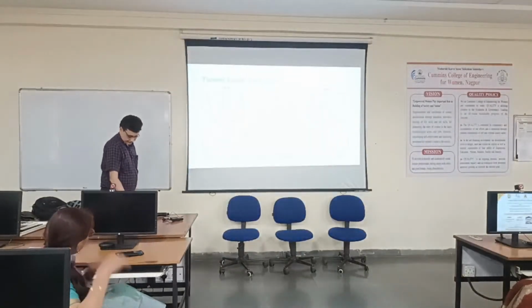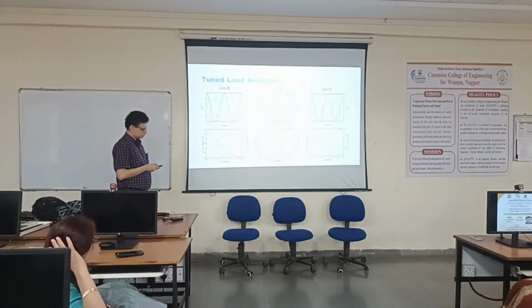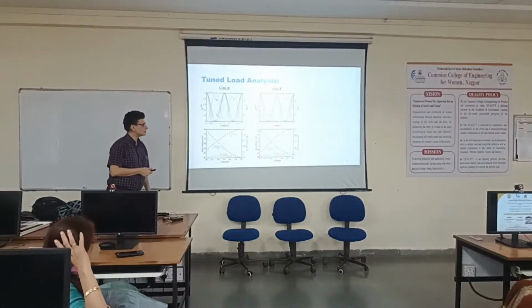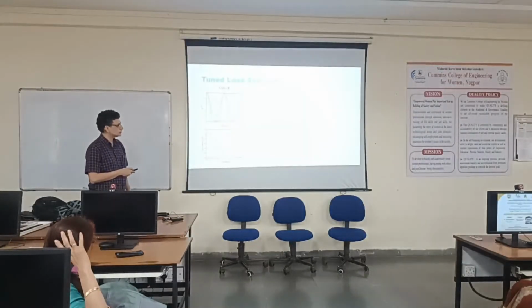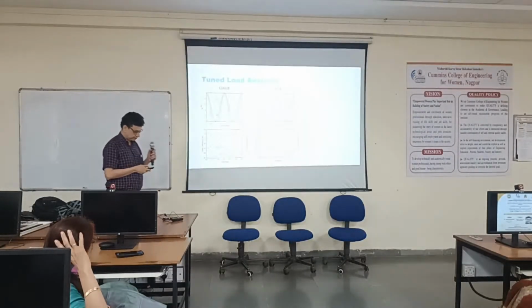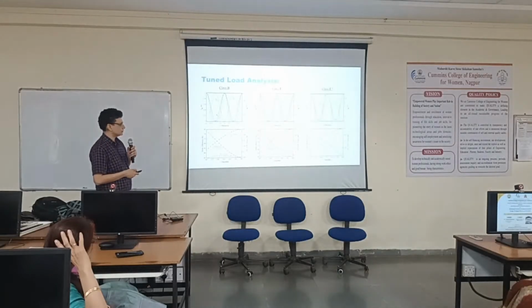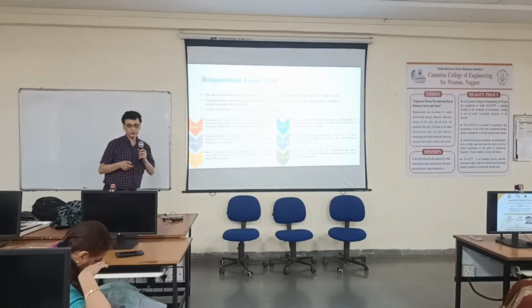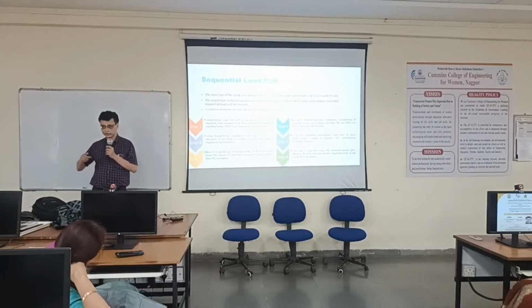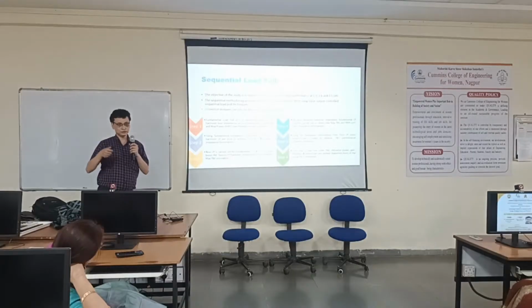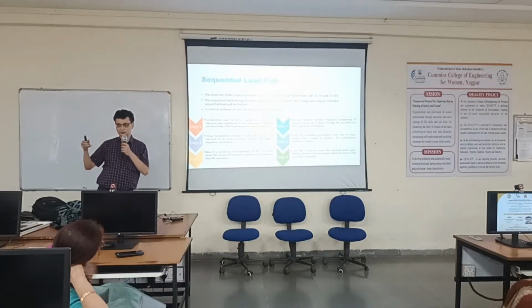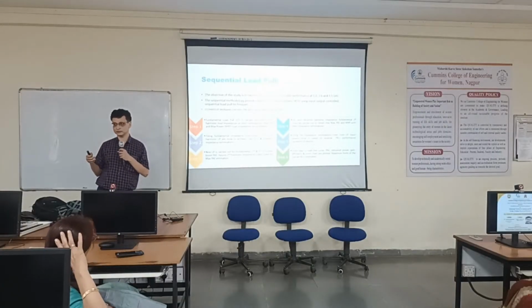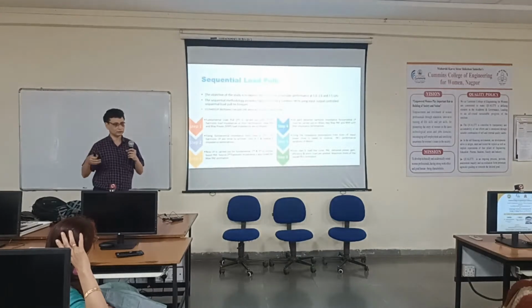So these harmonics, as I said, are the primary tools that we use to shape these current and voltage waveforms. So when we do load pull analysis, we not only do it for the fundamental, we sweep all possible impedances for the fundamental frequency and also for the higher order harmonics, so for the second harmonic and third harmonic.